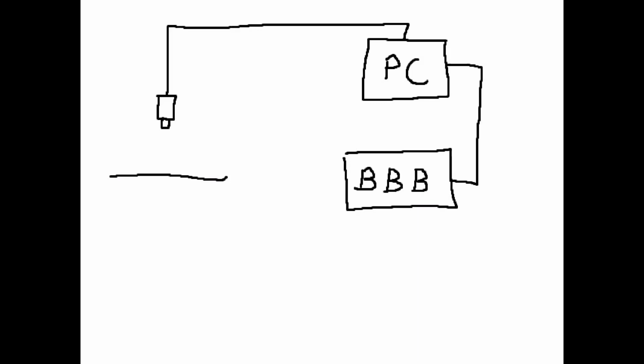The other way that the Beaglebone Black solves this problem is with the programmable real-time units, the PRUs. These are essentially mini microcontrollers within the Beaglebone Black itself. There are two of them, and they are very fast, 100 megahertz in fact, and can be programmed in assembly or C. Furthermore, they have access to the address space and I/O ports of the Beaglebone Black, so data can be fed in and out of them, and they can control their environment.